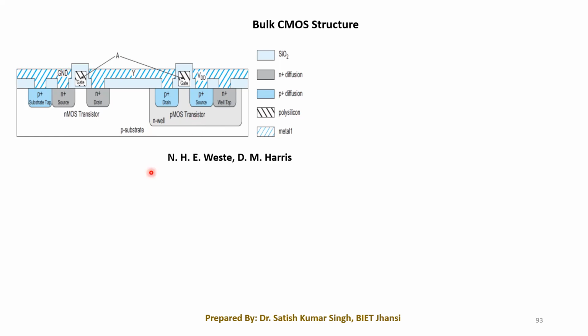So once we have this type of structure, we have to again follow the same fabrication steps that we have followed for the NMOS transistor. So please do not get confused by it. The same processing steps: multiple times we have to use the masking and photolithography operation, multiple times we have to perform the etching, and then finally we have to arrive at this particular structure.